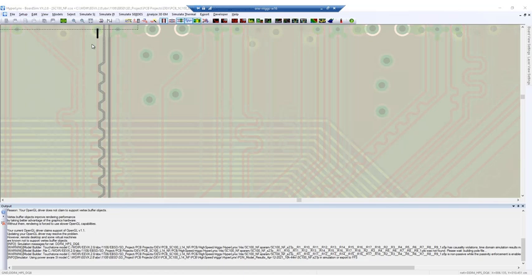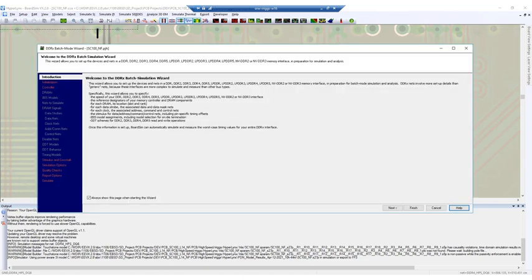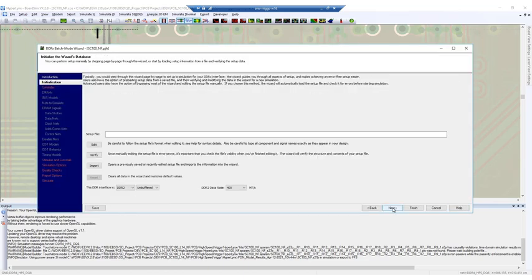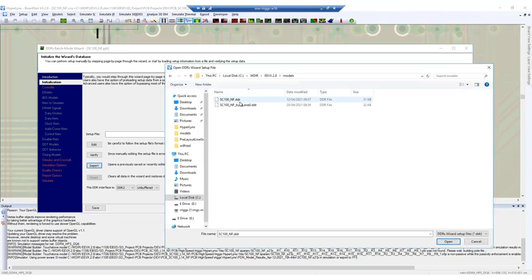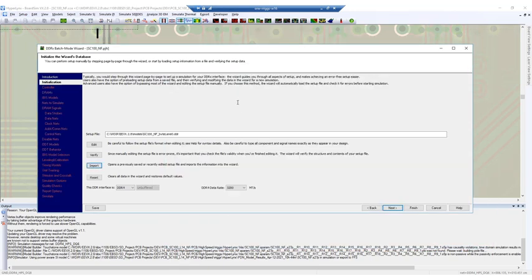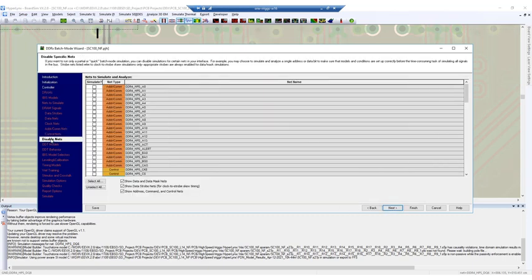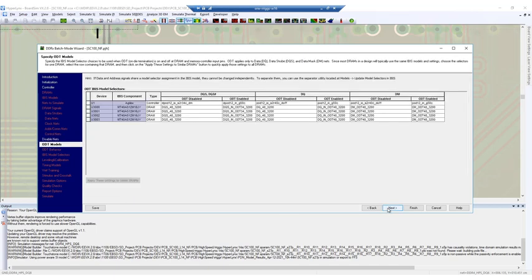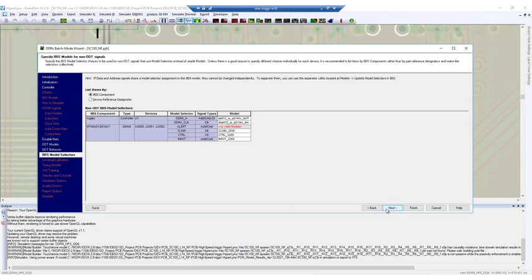Continuing on, I'll model one byte lane of the DDR4 to start, and then do this for all of the memory. Let's use the DDRX wizard to streamline the process. Remember, Wilfred, the PCB designer, ran the DDRX wizard earlier, but he was not modeling the effects that I'm modeling now with my power-aware model. I will include a crosstalk check as well.